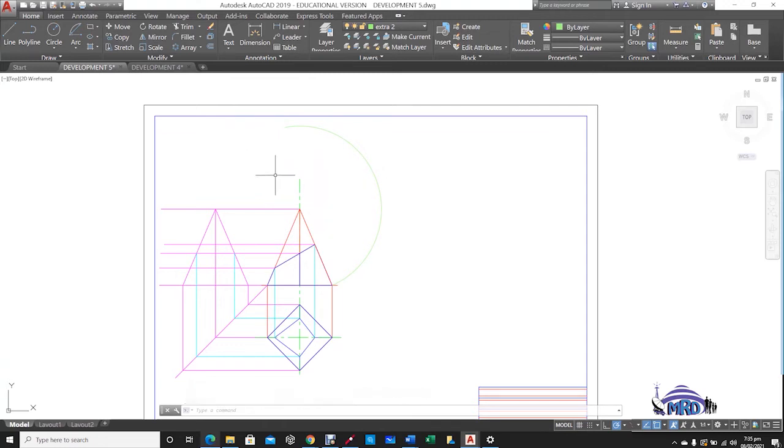We will need to produce another 3 curves because the slope will give us curves for the development shape as well. In order to pull these curves, we're going to have to bring the points on the sloping surface across to the side of the elevation, across to the side of the triangle, and the curves will pick up from on the side of the triangle.